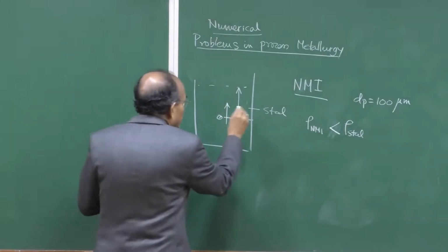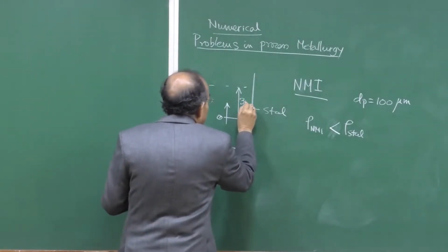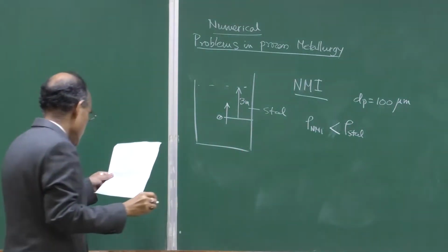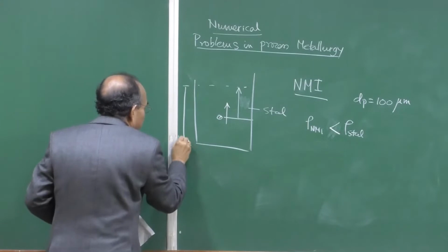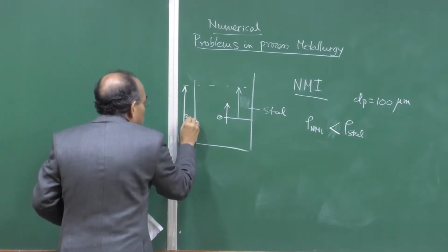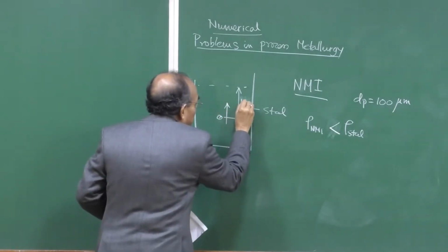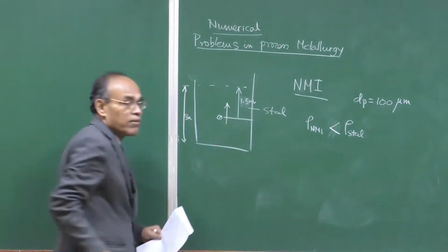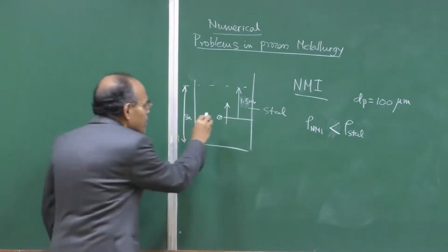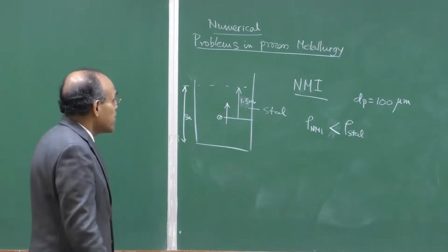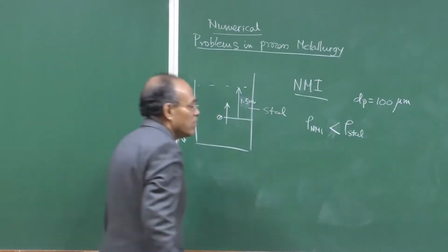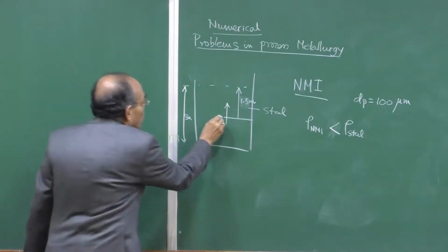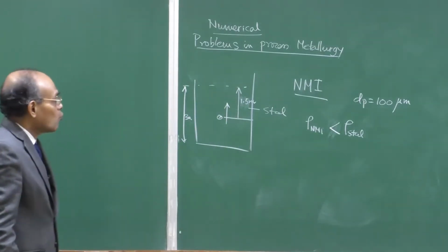This total of 3 meter is the typical bath depth of a ladle. So, from the mid bath depth level, it is 1.5 meter. Suppose a hypothetical inclusion is present at the mid bath level, and I want to find out, if the diameter is 100 micron, what the time taken to float out should be.